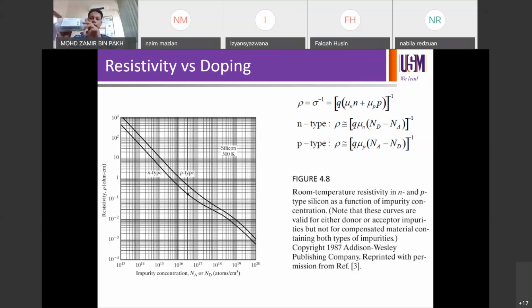Usually for lab scale wafers, if I buy for 1 to 10, it's going to be cheaper than if I buy the very same pack but with resistivity control of 1 to 3 ohm cm, right? So the tighter the resistivity control in the pack, the more expensive the pack becomes. So fair enough, 1 to 10 is fine in my case, but in some other applications, you might need to control between 1 to 2 ohm cm only, or else your device will show some variations.